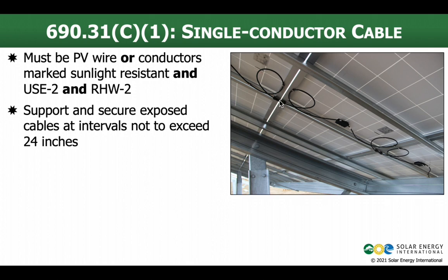What does that do? Well, that exposes that connector to more UV. It exposes it to more direct moisture. Don't love it. I would prefer to see this staggered, the connector tucked up in here or here. It's going to make the loops a little different size. They're not going to look quite as nice, but it's going to be a more reliable installation. Otherwise, I'm liking what I see as far as the wire management goes here.